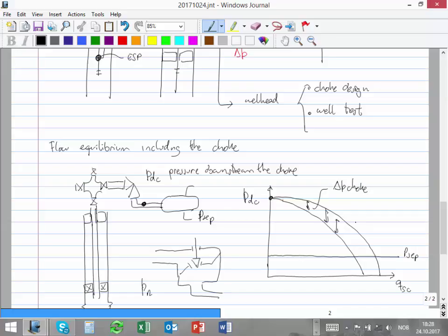So that's for 100% opening, and that's for 80% opening, and so forth. I reduce the WPR because it's another pressure drop. For now, look at it like that: I'm just changing the available pressure by closing the opening of the choke. But tomorrow, or maybe on Thursday, we are going to talk in more detail. Was that clear? Okay.